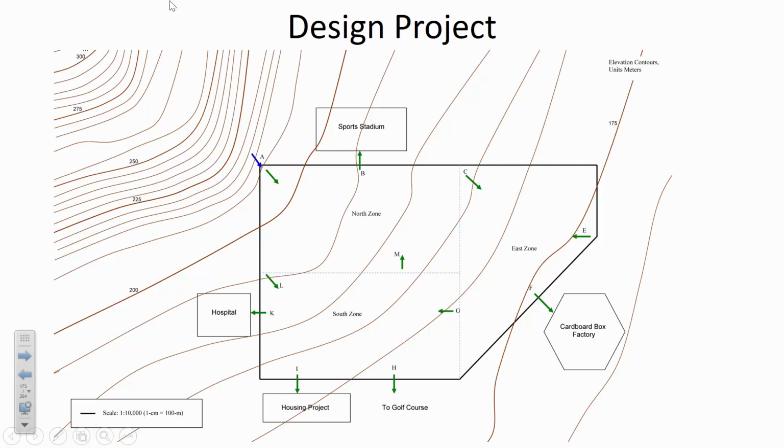So, during the design condition, which you can assume is the worst case scenario, when this entire land is fully built out. It's a mistake to design your infrastructure for the demands at the beginning of the project life, when no one has actually moved in yet. You want to think many, many years in the future, 25, 50 years, when this is fully built out. You want to make sure that the pipes are big enough to satisfy the peak demands during that time period. So number 1, it's going to be in the future.